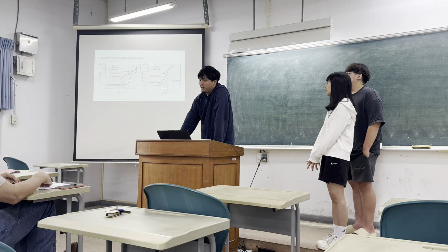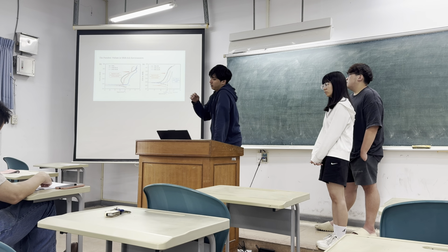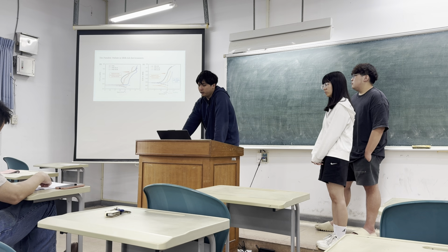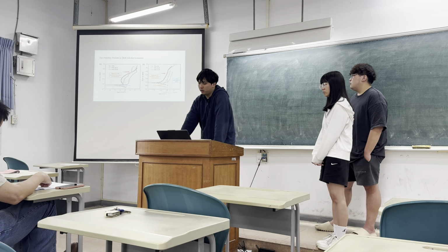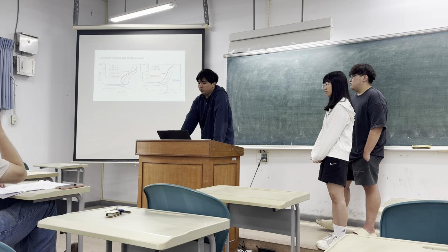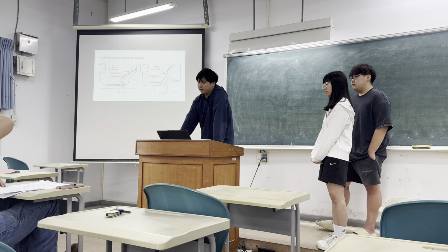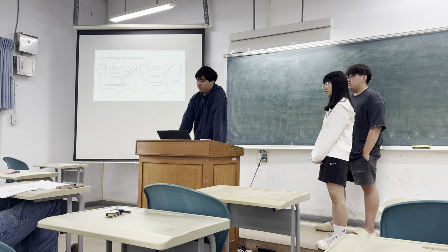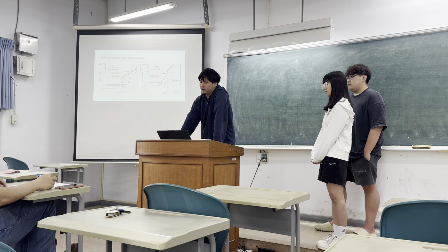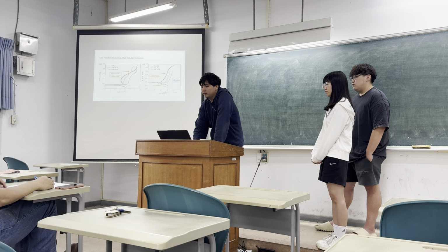Let's observe the curves in the SRB environment shown in figure B and figure C. Unlike the sterile condition, we see a distinct rightward shift of curves for all Cu bearing steel. This indicates a significant increase in the corrosion current density, meaning the overall corrosion rate is accelerating due to bacterial activity.